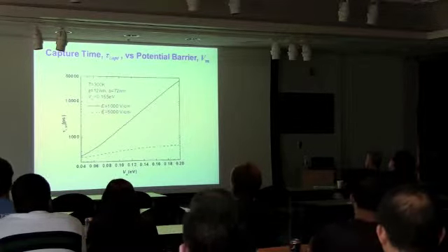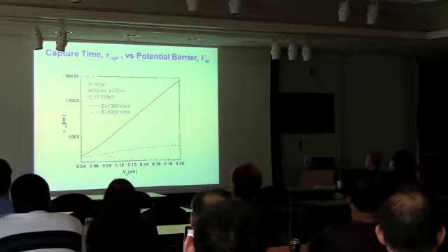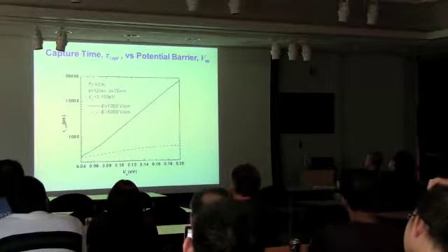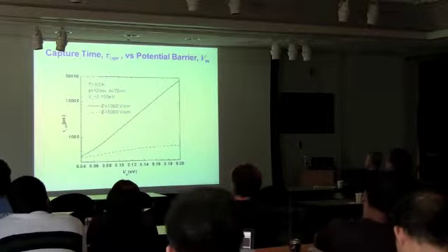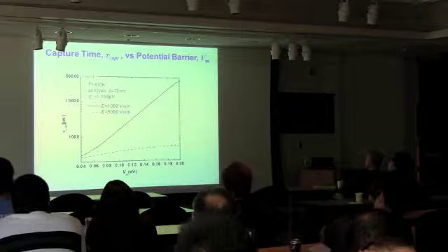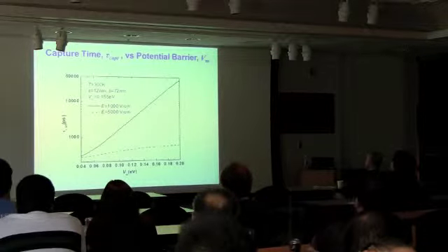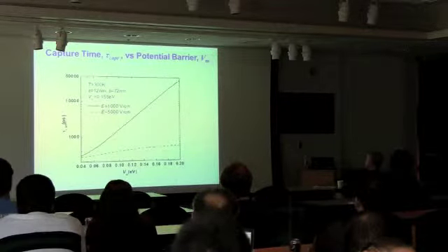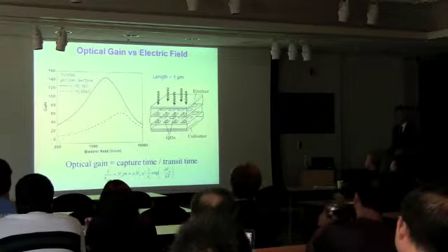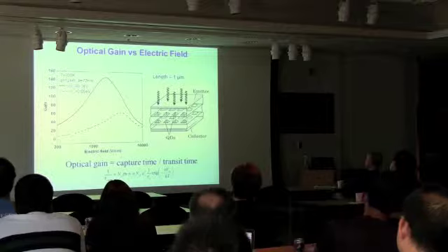And so here it is shown, like if we have a relatively low electric field, then the lifetime of carriers increases with the increase of the barrier height. If you have a very high field, then practically no dependence. Why is it? Because electrons are always very hot. They are moving at higher energies and can be really captured into the dots.